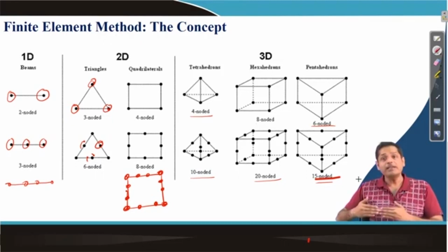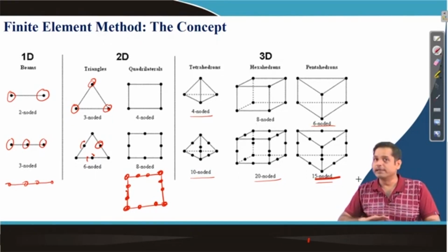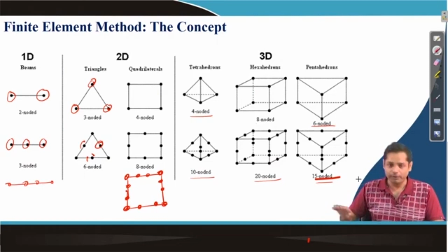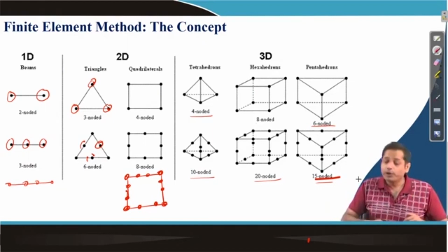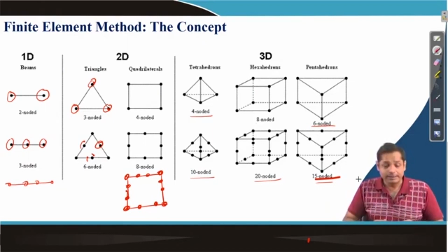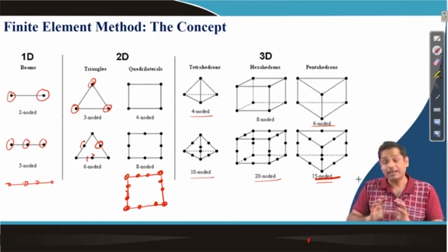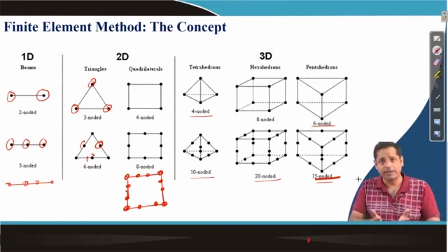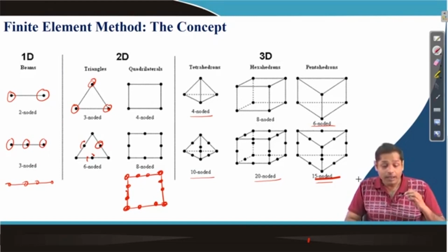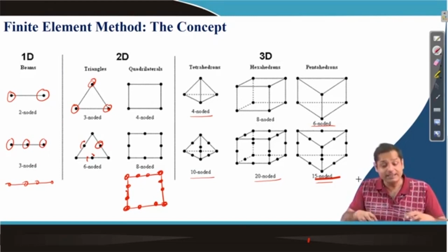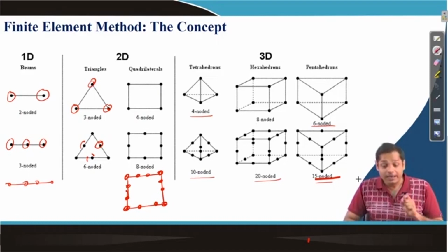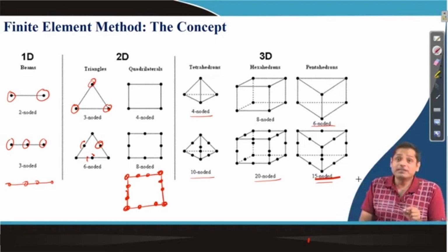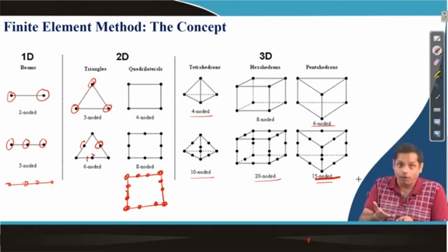Now, the premise of finite element, the basic philosophy will remain the same irrespective of the problem you apply. Then when you break it, the elements we use, as far as the shapes are concerned, these are the common shapes we have. But then once we discretize it, once we have divided the entire domain into elements, the element level equations need to be written. Now, these equations are essentially the governing equations of the problem.